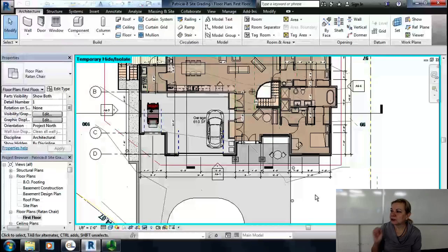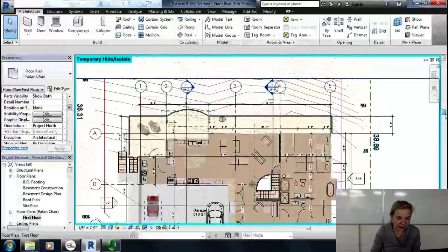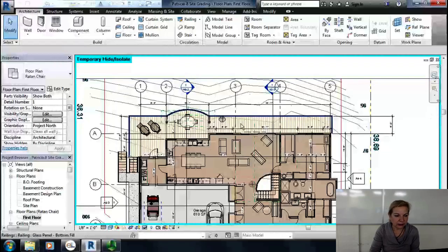Before I forget, for section drawings, for elevation drawings, please do not repeat these floor plan dimensions. On sections, we show dimensions between levels, your elevations, top of a floor to top of the floor, basement floor, ceiling heights, window heights, sill heights, top of the roof possibly. We show roof slope, but we don't show dimensions that belong on a plan. So ultimately, we're going to dimension plans first. I have a grid, and if you have done the grid, then you need to dimension between grid lines.